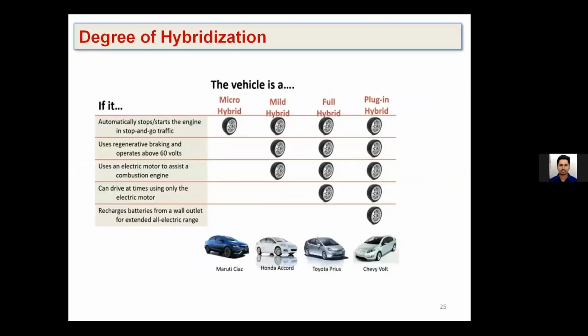So coming to the degree of hybridization: micro hybrid, mild hybrid, full hybrid, and plug-in hybrid. Coming to the micro hybrid with the start-stop feature, and the mild hybrid, it can support through braking operation. Even it uses some electric.